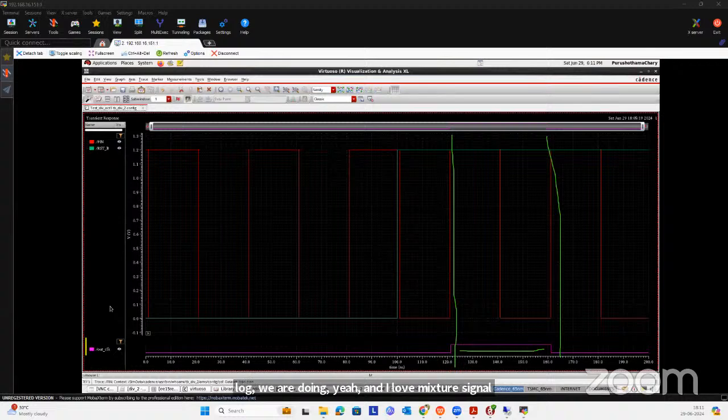Reset equal to 1 means out is equal to negation of out. Correct. So reset should be high. We have two kinds of things, active high reset and active low reset. So we have to define in the code whether it is active low reset or active high reset. Got it, Rohit? So we are working on the active high reset. These are detailed terminology.